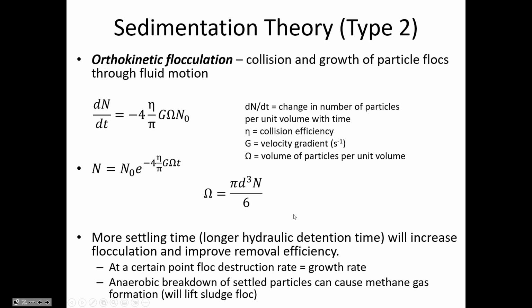But then the other aspect of it is if we leave particles too long in the clarifier, then they start to consume all of the oxygen that's in the water. And when they've consumed all of the oxygen that's in the clarifier, then they will begin to degrade anaerobically.